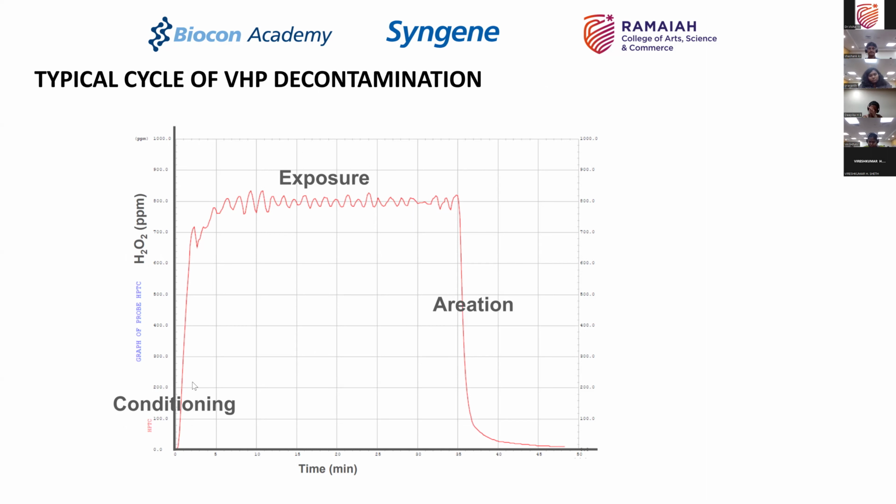What is important to write in a graph is the band in which you are allowed to operate. So you will have a line which says this is my lower tolerance limit, this is my higher tolerance limit, and as long as the sinusoidal curve is between those two lines, you have a proper exposure process. That is important to determine and specify and make sure it also appears in the graph.